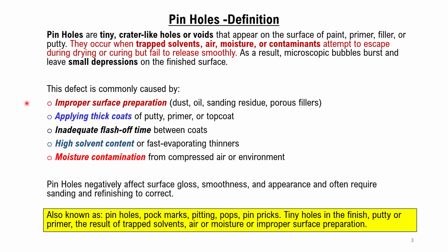This defect is commonly caused by improper surface preparation, that is, dust, oil, sanding residue, porous fillers, and then applying thick coats of primers or a top coat, or inadequate flash-off time between coats, high solvent content or fast-evaporating thinners, and moisture contaminants from compressed air or environment. Pinholes negatively affect surface gloss, smoothness, and appearance, and often require sanding and refinishing to fix it.